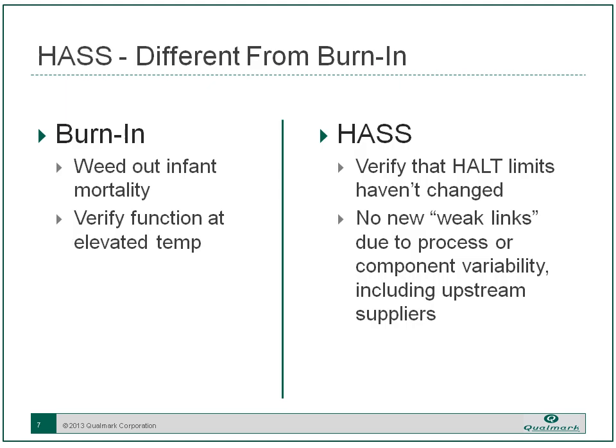Now, HASS is very different from burn-in, and it is not uncommon to have HASS replace burn-in in a manufacturing facility. The whole purpose of burn-in is to weed out infant mortality. Ideally, you're taking the first piece out of the bathtub curve. The effectiveness of it for doing that has been brought into question over the last several years because we've pretty much figured out how to build ICs, and that was one of the key purposes of burn-in, although it's still effective for high-power devices, and also verifying function at elevated temperature.